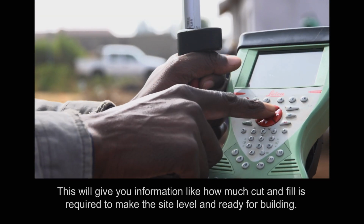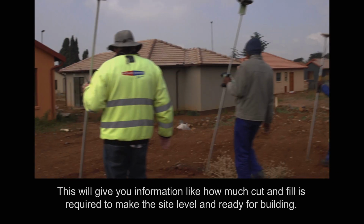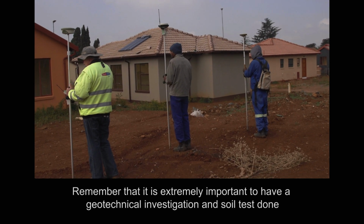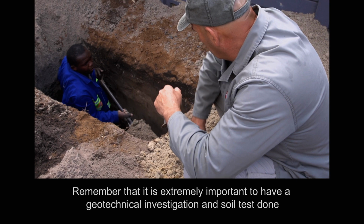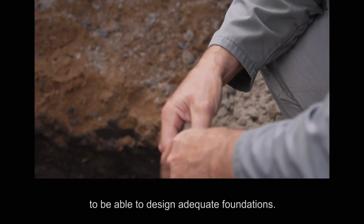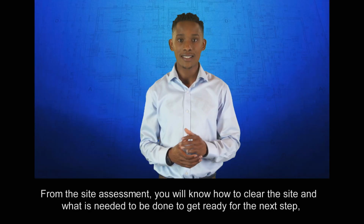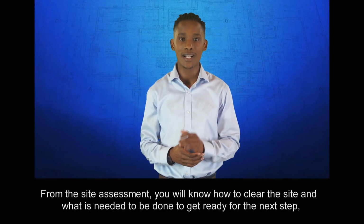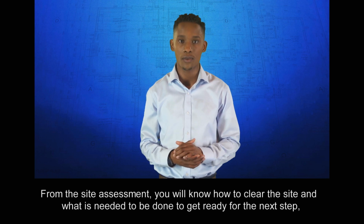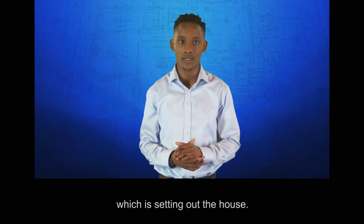This will give you information like how much cut and fill is required to make the site level and ready for building. Remember that it is extremely important to have a geotechnical investigation and soil test done to be able to design adequate foundations. From the site assessment, you will know how to clear the site and what is needed to be done to get ready for the next step, which is setting out the house.